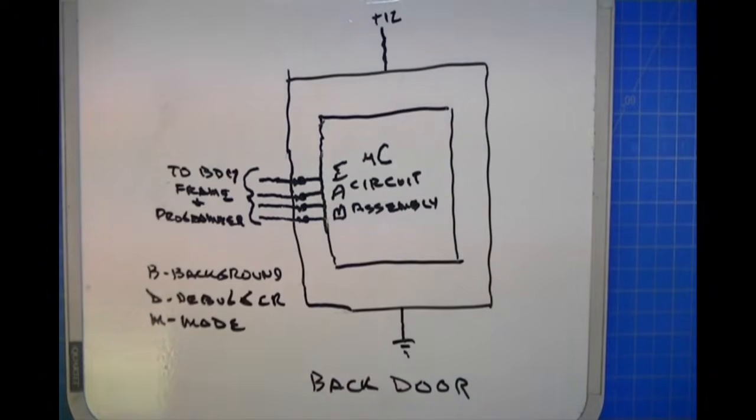What happens is the background debugger tool will actually go in and send commands onto the silicon of the processor, but they're not program commands like the processor would normally be running. The processor will still run its program as part of its normal operation.